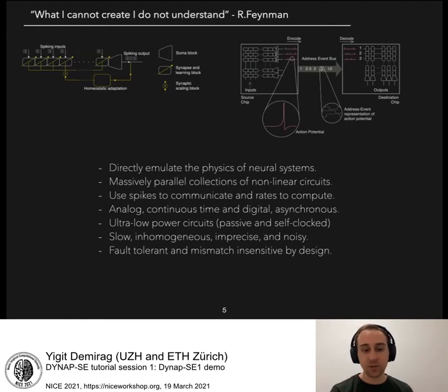And we work with exponentials and logarithms, just like ions crossing the ion channels in neurons. The neuromorphic processors that we are building are essentially very large arrays of massively parallel analog circuits that implement thousands of neurons and synapses. And one important point here is that this is not a number crunching system. This is a really massive dynamical system that works in real time.